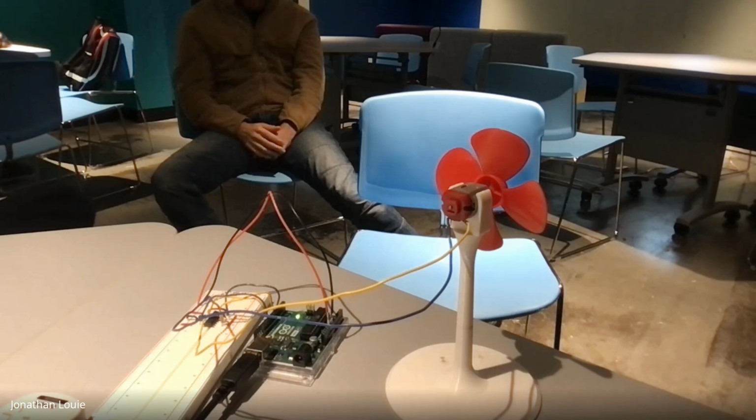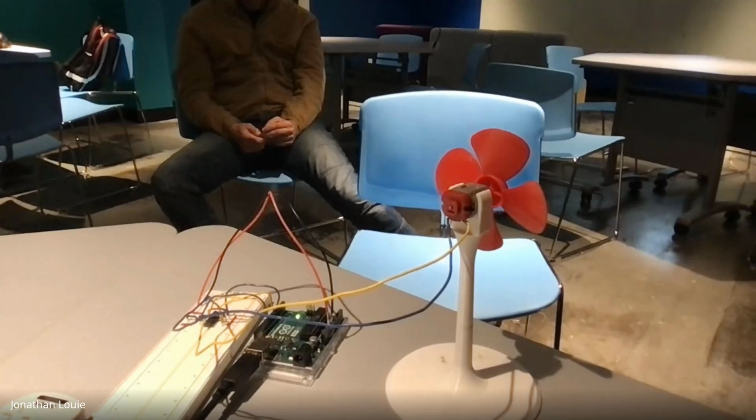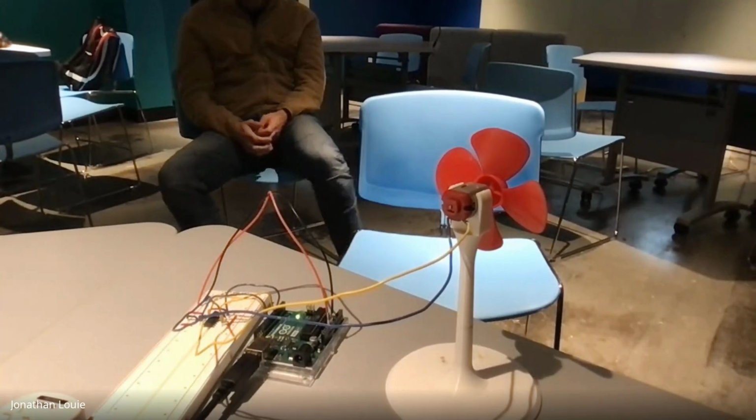So you have to be careful with the speeds of these things. Emissions as in dangerous emissions? No, no. Emissions in the sense that you get two wires right next to each other and you try switching one of them at really high speeds. The wires at high speeds will couple to each other. So some of that signal will go from the first wire to the second wire. Oh, interesting. And it'll start messing up your signal. It'll cause noise.